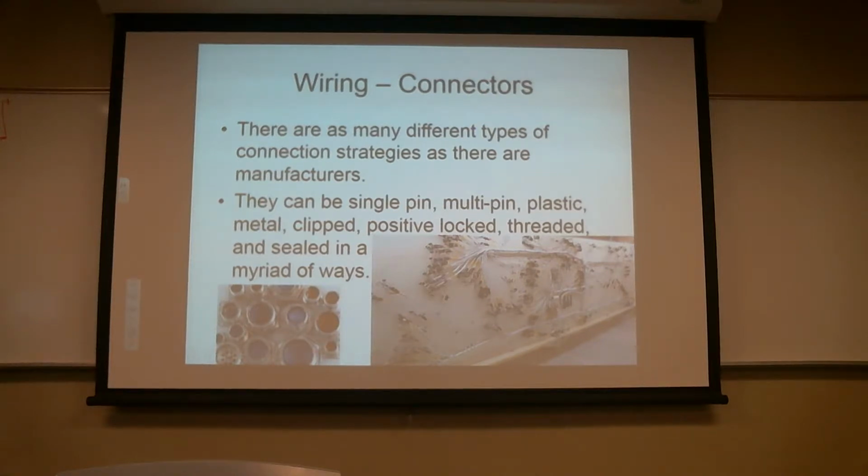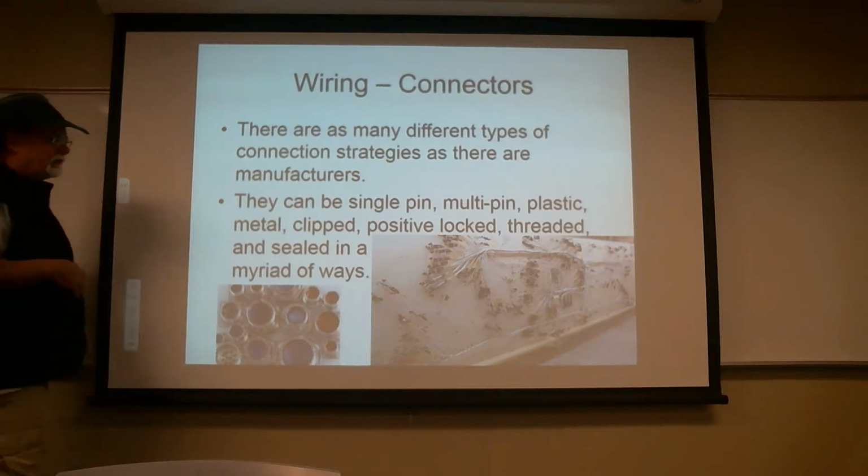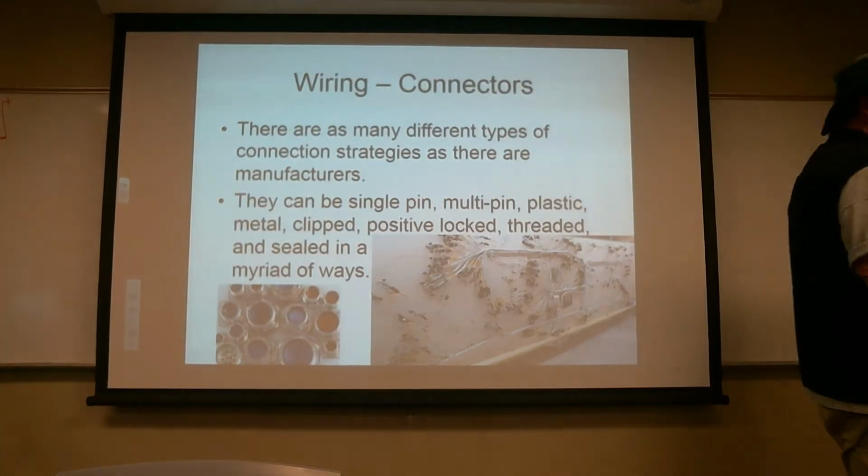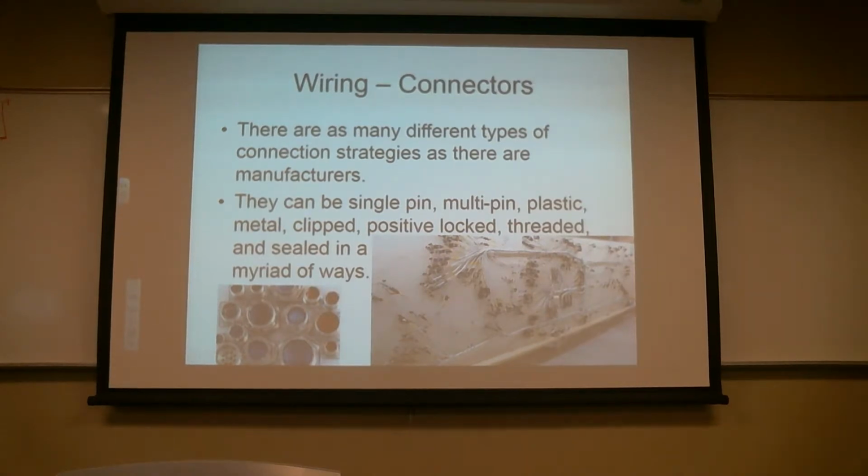So when we're building up a wiring harness, we'll first design. We'll get dimensional parameters from the builder of the airframe, the automobile, or whatever, and we'll get some basic length dimensions for all the components and the runs.